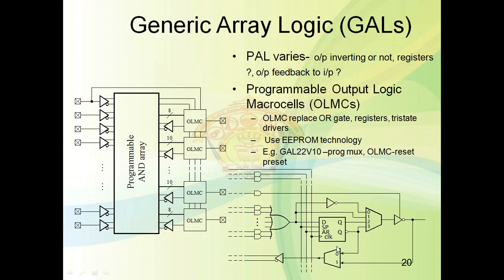So see here, it will have 4 outputs. That is, you will get the direct output, the inverted output, the registered output, and the inverted registered output. Means direct output and registered output, in inverted and non-inverting form, will be there. By using select pins, we can select a particular output pin. And that will again be controlled by an output enable logic here.